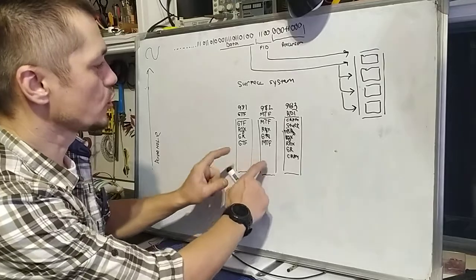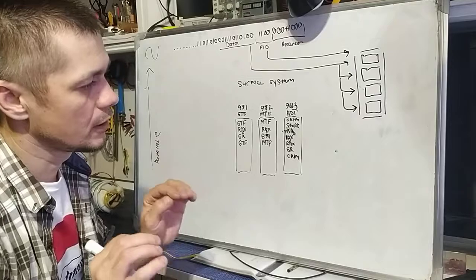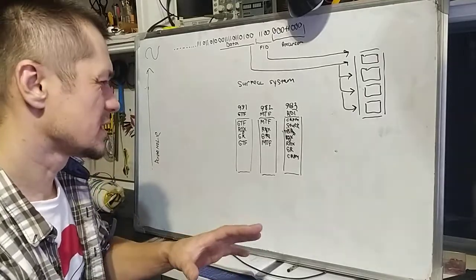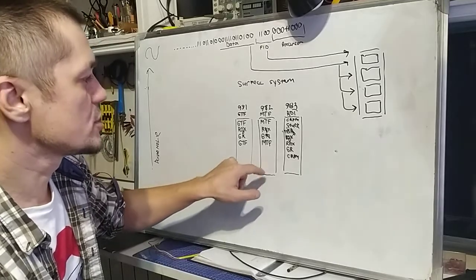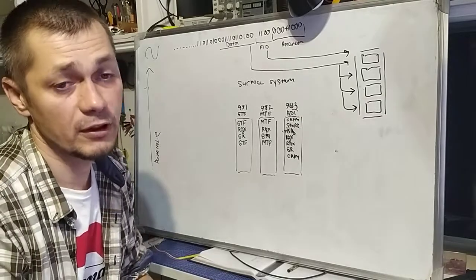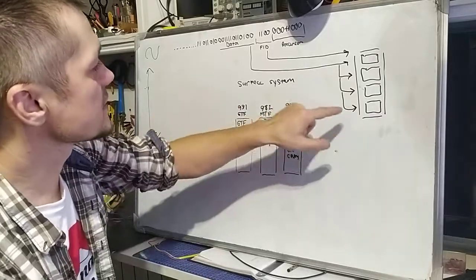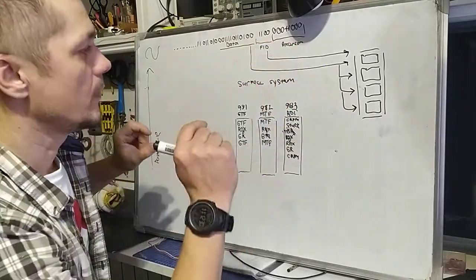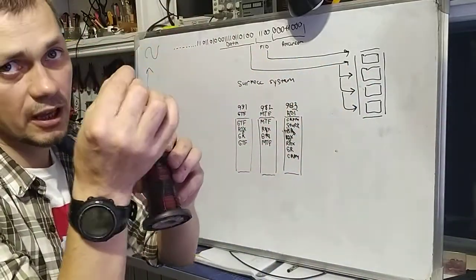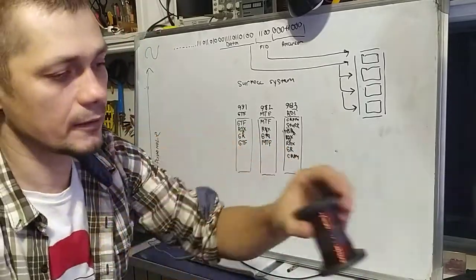The tool will switch automatically, or sometimes you have to switch manually. It depends on the tool, on the software system of the company, or whatever. But most of the time it switches automatically between GTF and MTF, depending on whether you have zero angle, vertical, or a deviated well. So what happened? The surface system got the precursor. Okay, from this point it found the beginning of the information. So now it starts reading it.